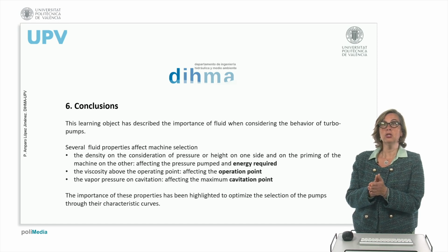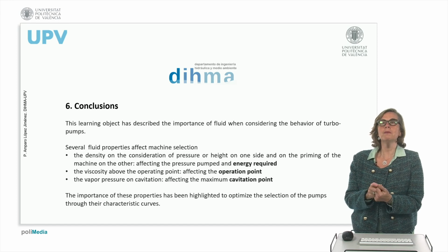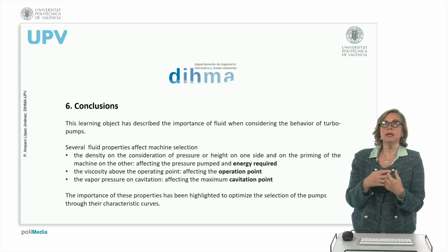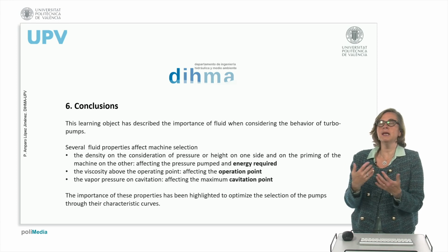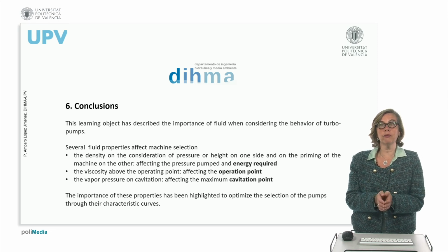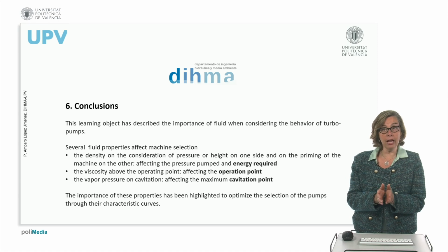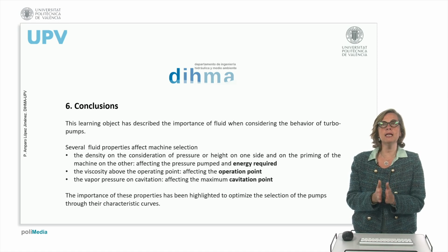So if we buy a pump to work with water, we must consider very well what will happen with other fluids, let's say benzene, let's say oil, in order to know how the behavior will be with different fluids, which surely will affect the operation point, the cavitation point, and the energy implications of the pump.